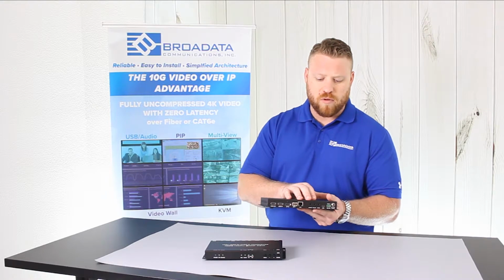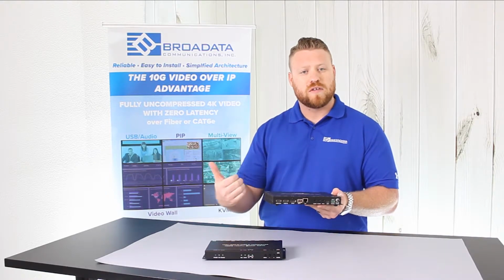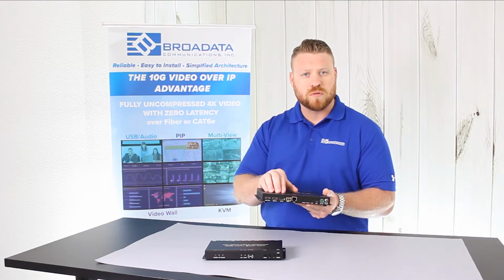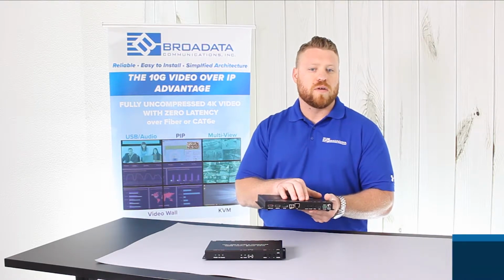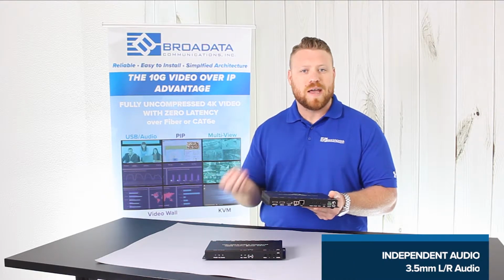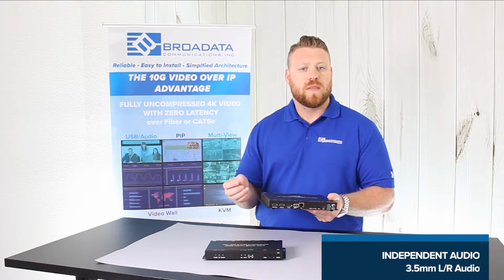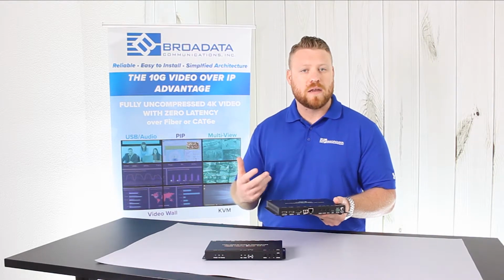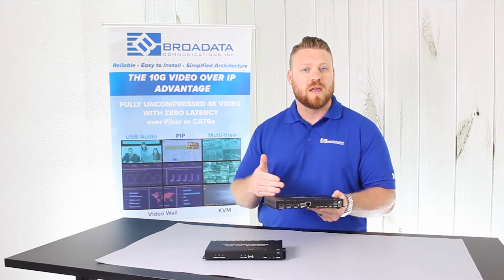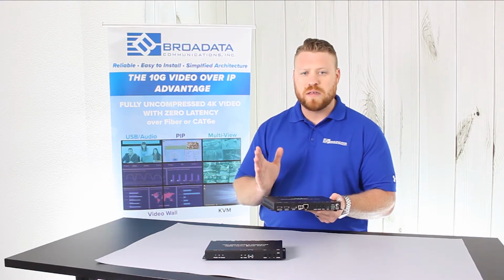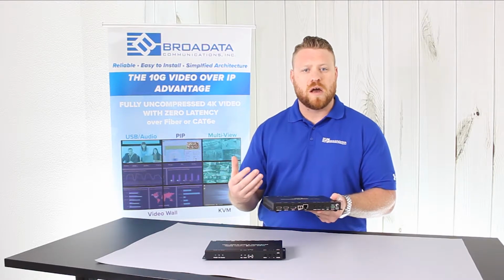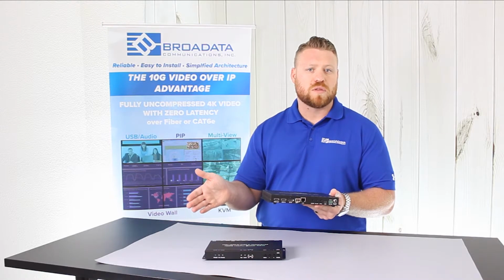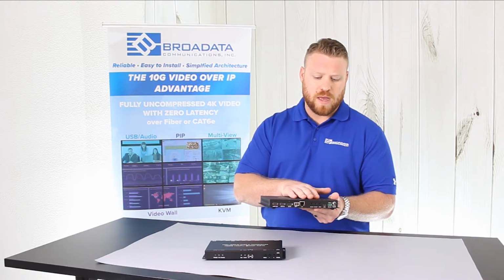It does have a separate audio input. So additionally to the digital video and audio provided by HDMI or DisplayPort sources, I can have additional audio input into my system that is independently routed or routable. That does not necessarily get embedded or follow the video, although it can. You can set it up that way. You can embed the audio, or you can keep that completely separate, put it onto a Dante audio network, take that however which way you want to, put that into a digital DSP if you'd like. Okay, so that helps us out there.